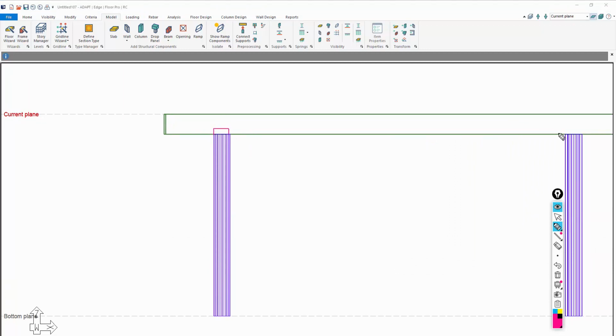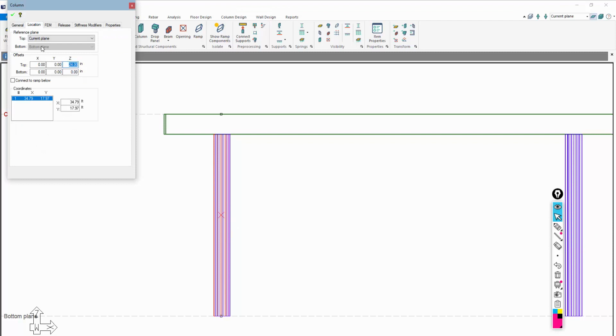the mat. If I extend them upward, what I would do in that case is select the pile like so, and at the top here I would do an extension down of the depth of the mat minus the socket. So if this might be, for example, a 4-inch socket, I'll do a 20-inch extension, something like that. So that's the first step.